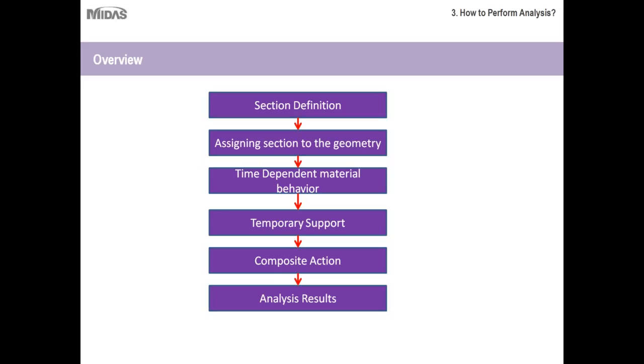And this is the layout for the demo that I'll be going through today. I'll start with the section definition and then assign that section to the geometry of the bridge. Then I'll be defining the time-dependent material behavior for this particular bridge.